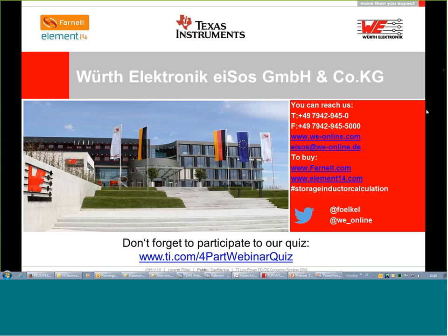One experience I had which did not help was turning around the inductance. I found out, okay, the colleague did use a duty cycle which was not so good, and as soon as we changed the duty cycle, it was already much better, and the sound was gone. So actually, if you are using that kind of pulse mode, sometimes it could happen, yes.